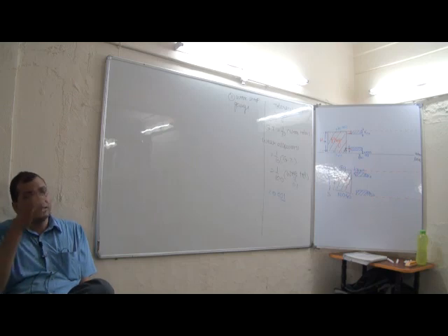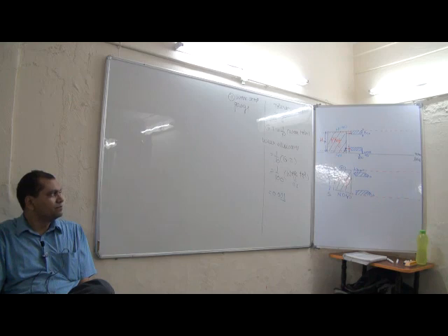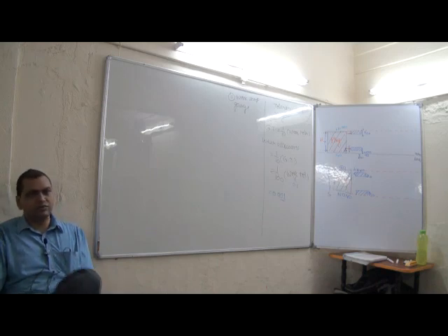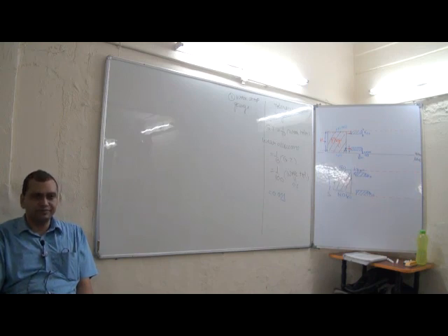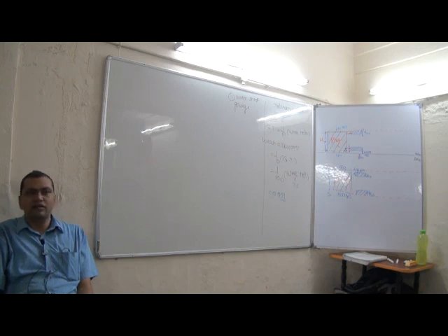Next sentence, underline. So to increase the life of the go gauge, we provide wear allowance. Wear allowance will not be provided on the no go gauge. It will be provided only on the go gauge. Full stop. When the work tolerance is less than 0.1 millimeter, we don't provide any wear allowance.